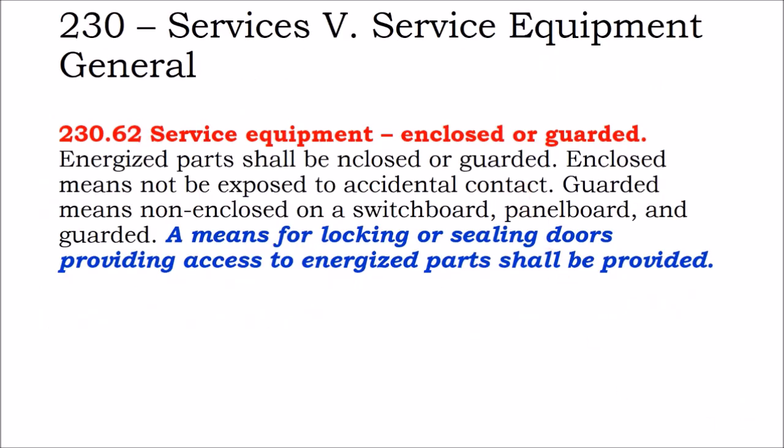Services. Service equipment enclosed or guarded. Energized parts shall be enclosed or guarded. Enclosed means not exposed to accidental contact. Guarded means enclosed on a switchboard, panelboard, and guarded. A means for locking or sealing doors providing access to energized parts shall be provided. So energized parts need to be enclosed and guarded.